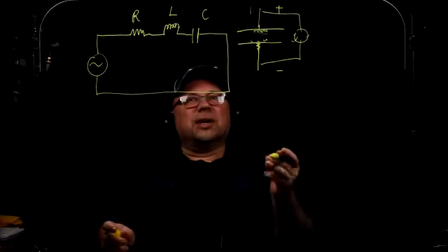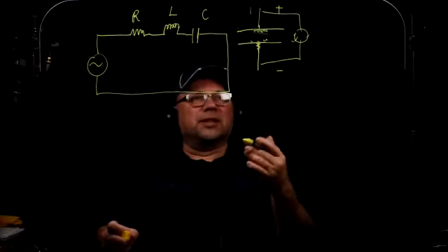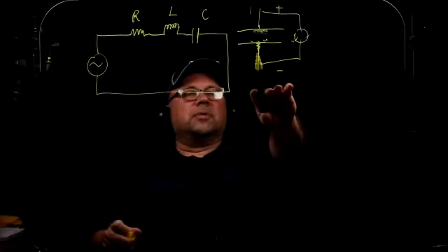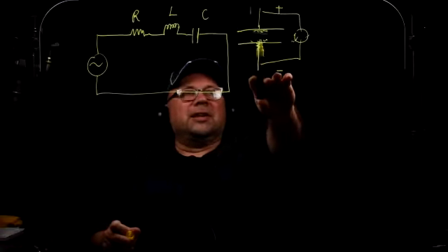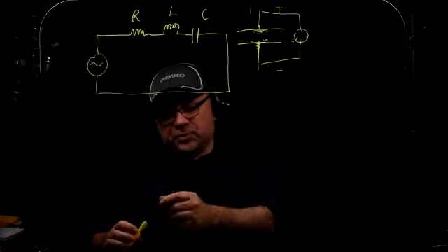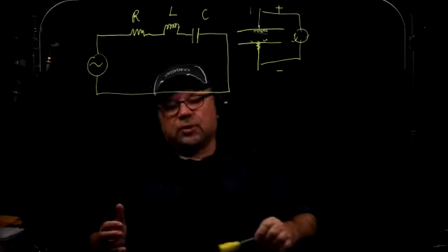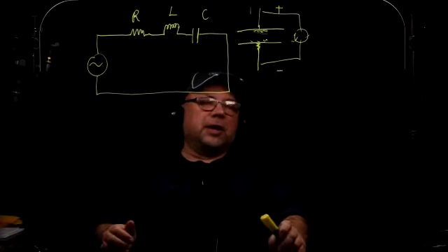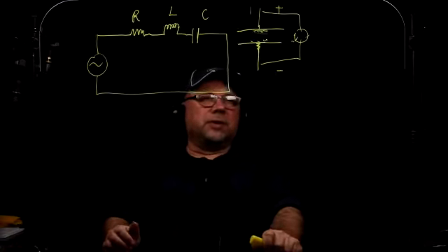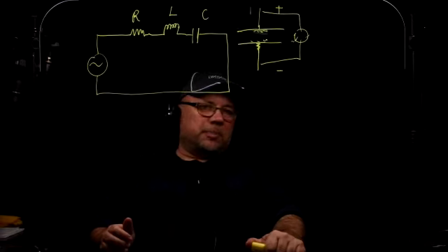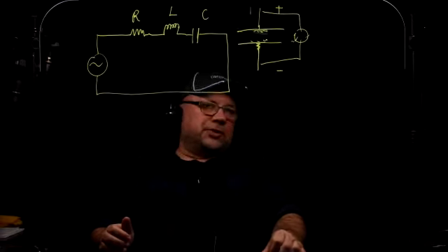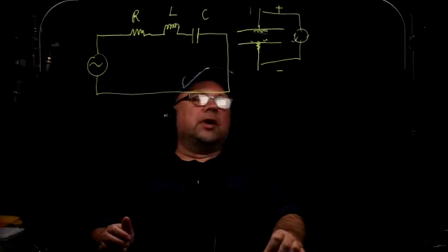Yes, it's going to have some inductance, but it's negligible, so let's forget about that. Now, the combination of the resistance and the reactive resistance, because capacitors are reactive, their resistance depends on the frequency. The higher the frequency, the less resistance the capacitor is going to have. The lower the frequency, the more resistance the capacitor is going to give you.